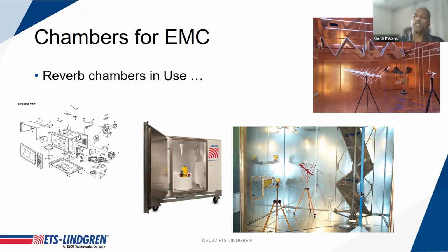The downside is it takes a long time to do that. You have to store those modes and take lots of samples to get the uncertainty down when doing that. So again, it's a trade-off between test time, test cost, and measurement uncertainty. And if you can offset uncertainty by over-testing, increasing the field levels that you test to, then in some cases, that's an acceptable compromise.